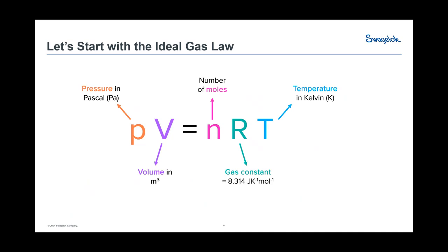So a couple of weird things about it. First of all, I mentioned propane tanks earlier. If you run a large pressure drop off of a propane tank, you'll notice ice on the outside of it. It gets cold. Hydrogen actually gets hot. That's one of the really interesting portions. That's why we start fueling vehicles at minus 40 degrees. A few of the other things are that as you add pressure, it compresses, and it changes how these formulas work. And I'll show you that real quick. We're not going to do a lot of math today, but I'll just give you an idea how this works.